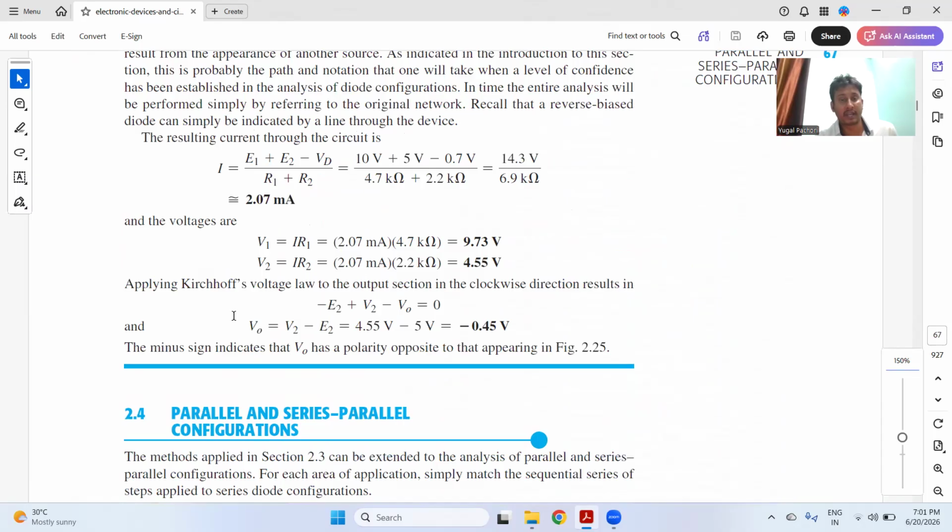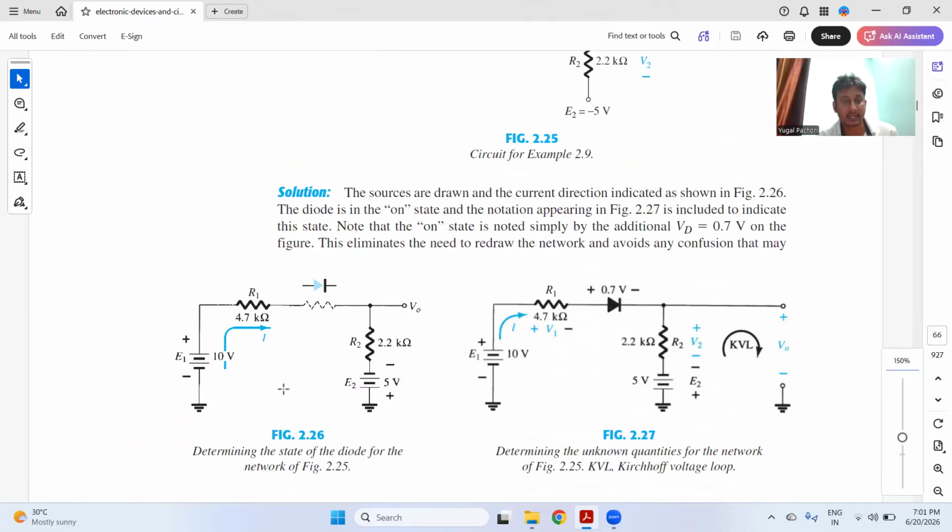This is it. So now look at this one more circuit. There is a voltage and there is a resistance. This is a diode. This is on. So there is some resistance of the diode, and hence there is one more resistance and there is one more voltage of opposite polarity. So with the current law, you will start from the higher voltage, 10 volt. You will move in this direction from 10 volt to 5 volt. Again, this will be resistance. This is the drop across the diode, which is 0.7.